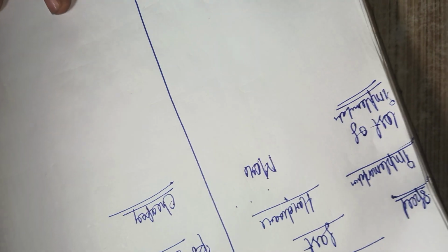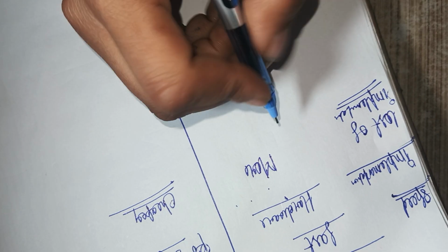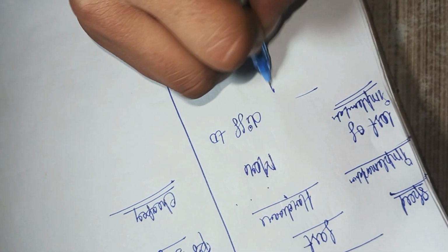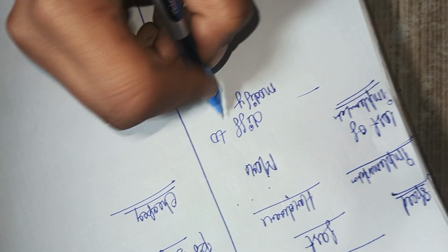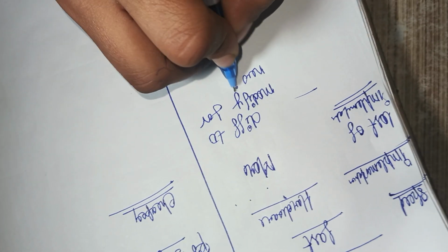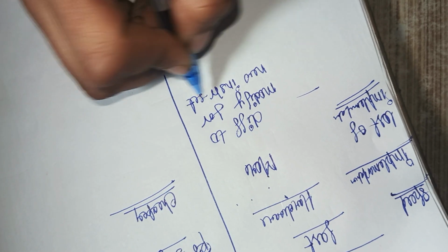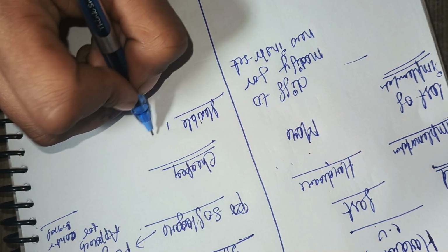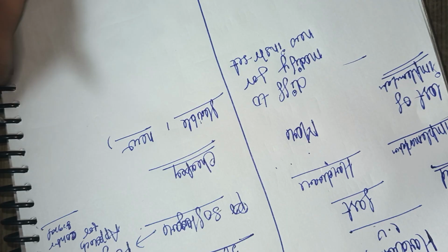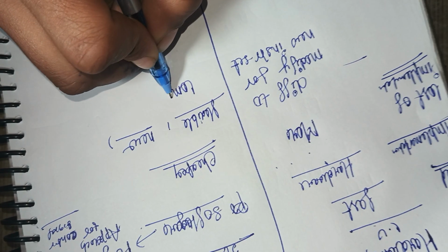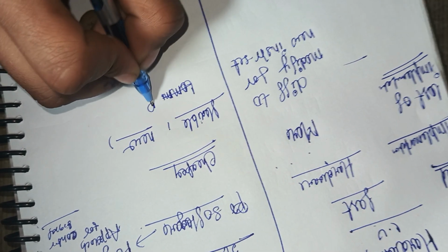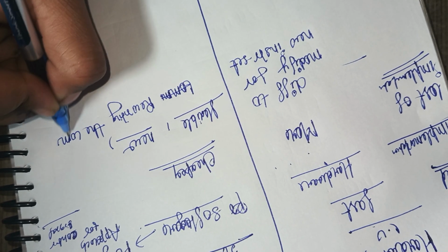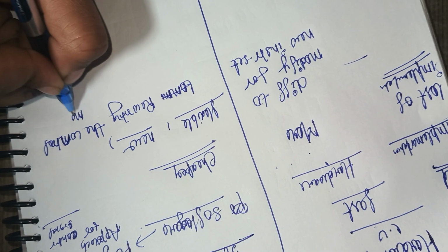And if we talk about flexibility, the hardwired one is not flexible and is difficult to modify for a new instruction set. The microprogram one is flexible, and a new instruction set can be easily modified by rewriting the control memory.